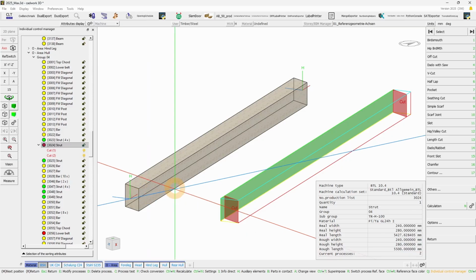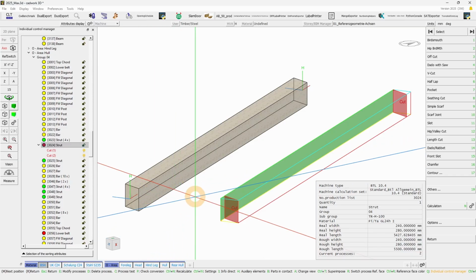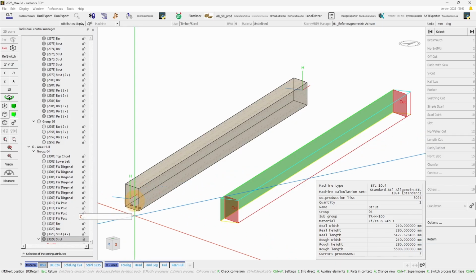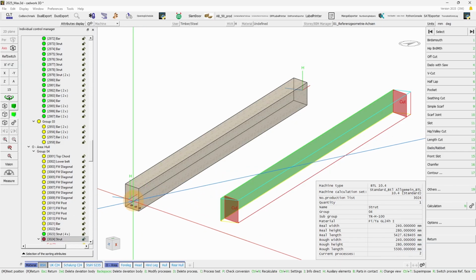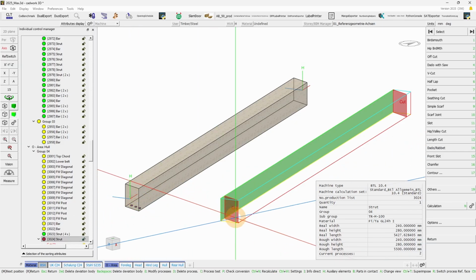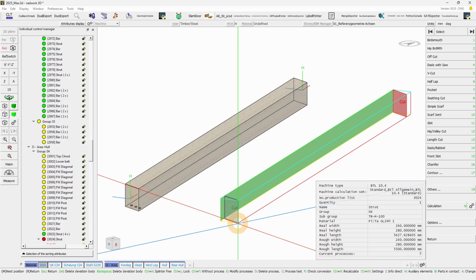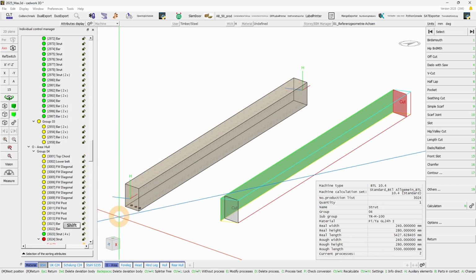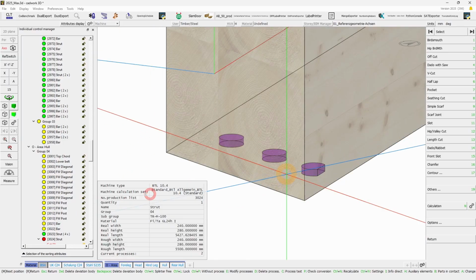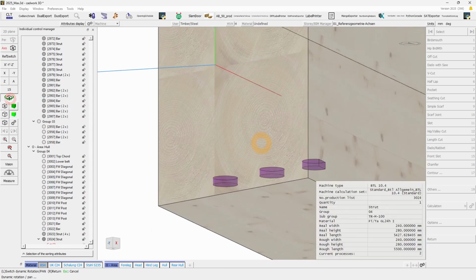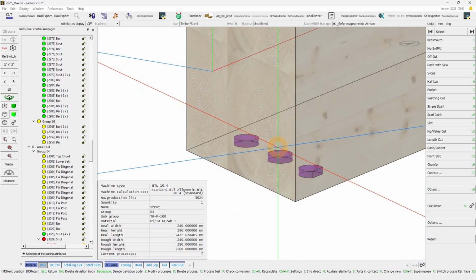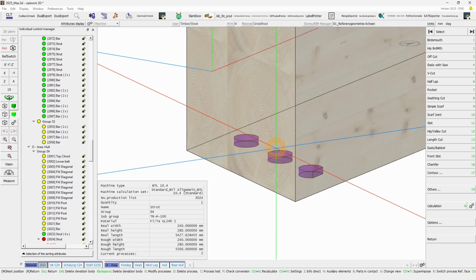So in that case here we could press C to run the process again on that item, and Cadwork is going to show you here what we call the deviation body, simply the processes that are missing from the calculation. You can then easily zoom on them using Shift Lasso, and whether this is relevant or not, you can actually adjust your calculation accordingly or simply disregard this result.